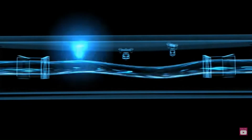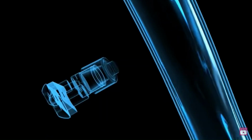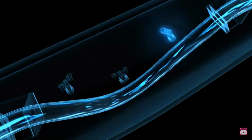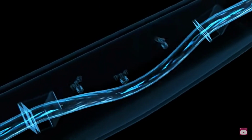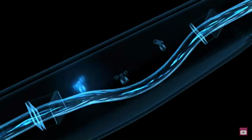Now, due to the Coriolis effect, the inlet and outlet sections of the tube oscillate in different directions at the same time. The highly sensitive sensors pick up this change in the tube oscillation in terms of time and space. This is known as the phase shift and is a direct measure of how much liquid or gas is currently flowing through the pipe. The higher the flow velocity, and thus the total flow, the greater the deflection of the oscillating measuring tube.